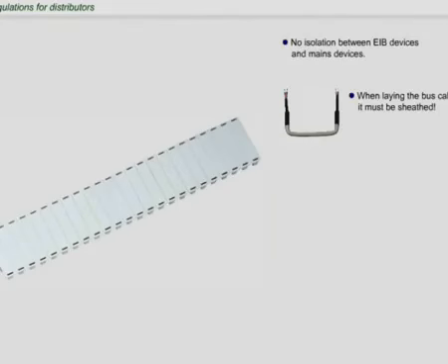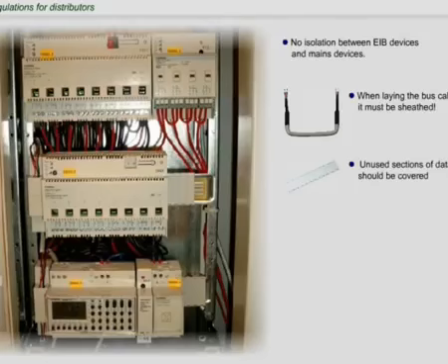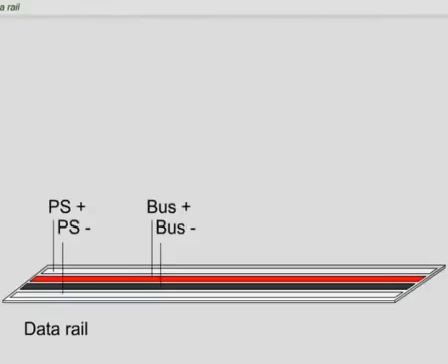Unused parts of a data rail must be protected by cover strips. In this way, no accidental contact to the mains core occurs, and this normally would damage all EIB KNX devices of a line. Data buses offer an alternative means of connecting the bus users in the hub. With these data buses, the connections are made automatically when the series devices are snapped in place.